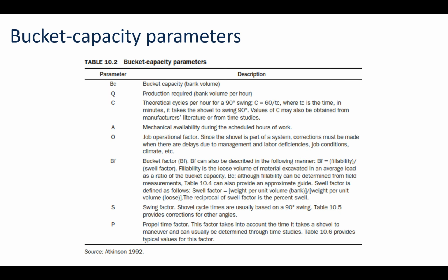And so here we have a huge list where BC is the bucket capacity. In bank volume, so bank cubic yards, that means in place cubic yards. Once you blast it, then it will take up more volume, and that includes what we call swell factor. So we're calculating it in bank yards.